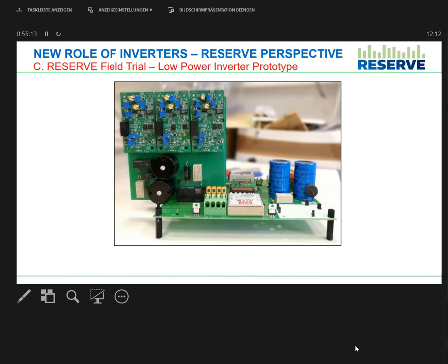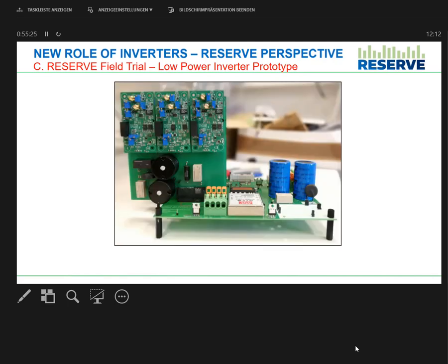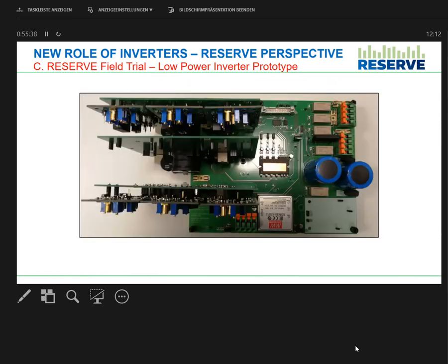So this is the LCL filter board with the measurement cards plugged in. As I showed here, this is one measurement card for DC link voltage measurement across the capacitor. Here you see that the filter board cards are plugged in at right angles, and all the connectors which connect to the grid and DC link are in this main board. So just a top view to clearly show the filter board on which the measurement boards are plugged in. So that's our setup.